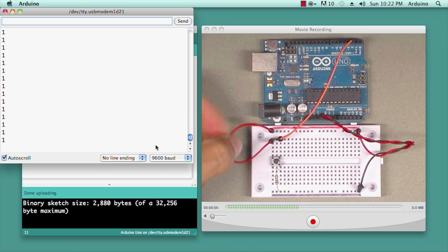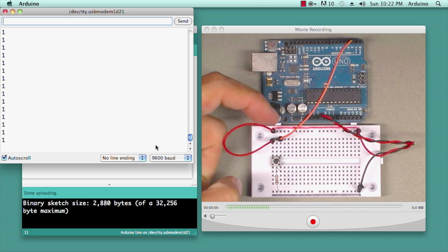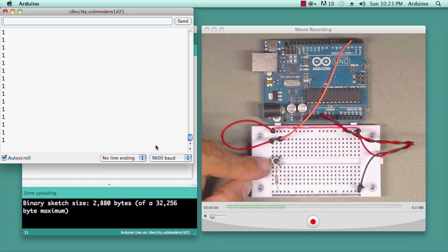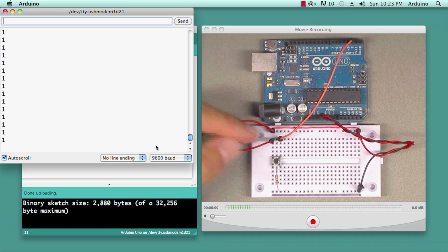And then as a double check, we want to make sure, does this circuit we've created have any possibility of a short circuit? That is a direct connection between power and ground. So here's our power bus. It comes in here. The only way it can get down to the ground is through the switch and through, guess what, this very large resistor. So the resistor is there, in part, to keep there from being a direct connection between the ground and the 5-volt bus.